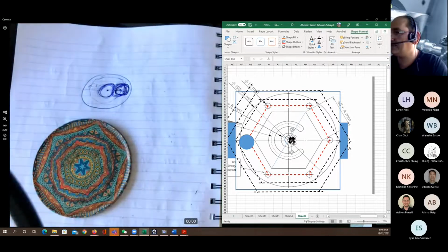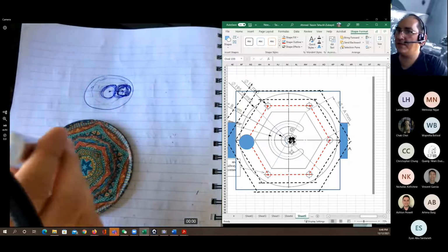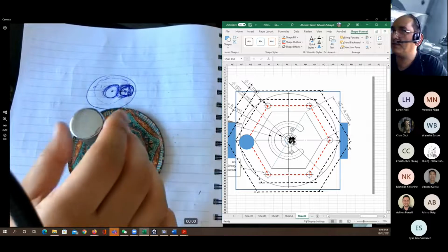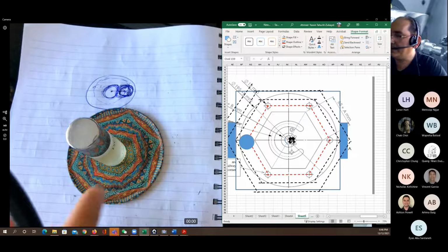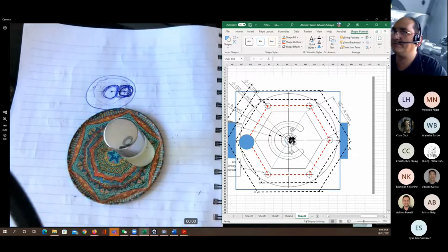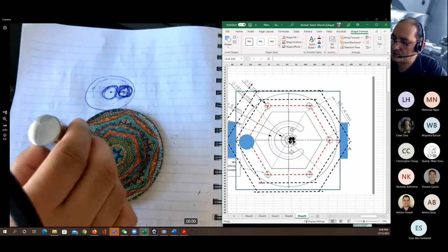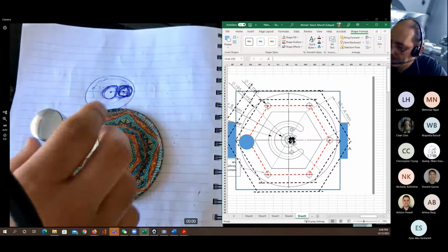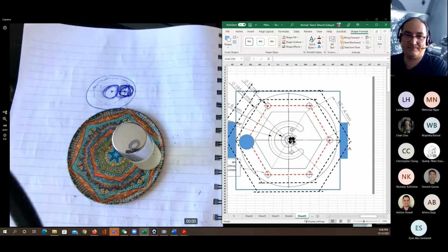Let's imagine that this is the pocket. This is my cutting tool. It will come to the middle first and drill a hole. Then it will go to the side. Then with the G02, it will move to this position. And then it's going to move to another position, finishing the cleaning. Easy? Yeah, makes sense.